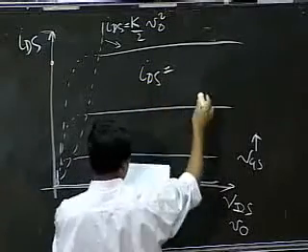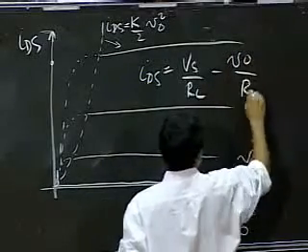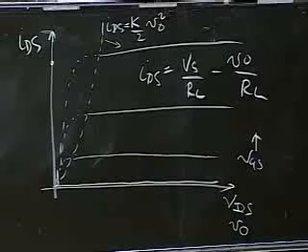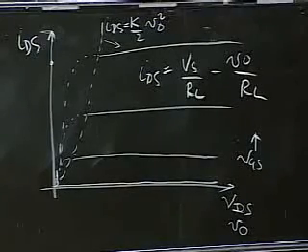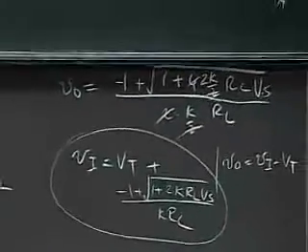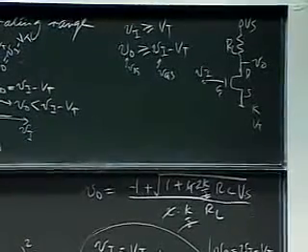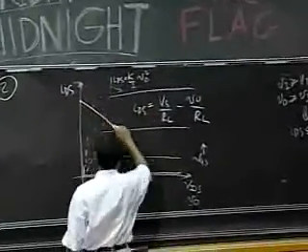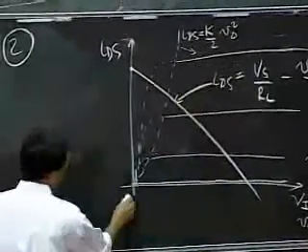My load line equation, if you recall, was IDS equals (VS minus V naught) divided by RL. This was simply obtained by writing KVL at the loop containing the output node and the supply VS. Notice there that V naught is equal to VS minus IDS times RL. Okay, and that's simply by dividing by RL on both sides and moving IDS to the left-hand side, we get this equation. And this equation gives rise to a curve that looks like this.